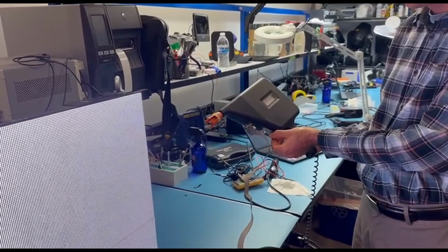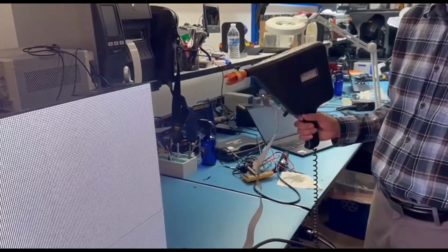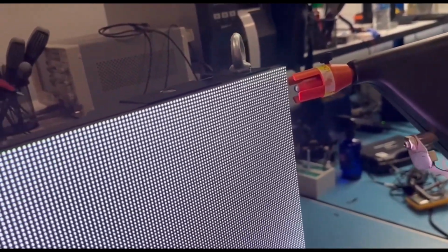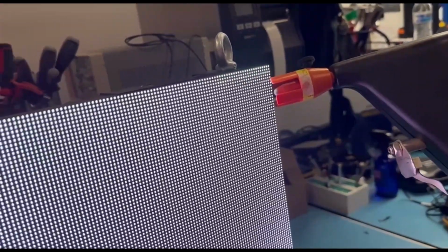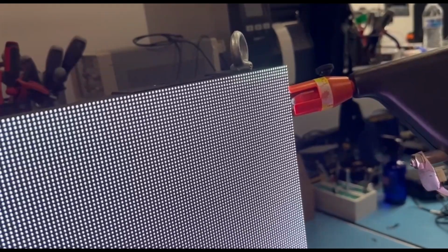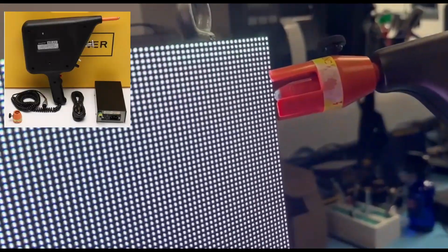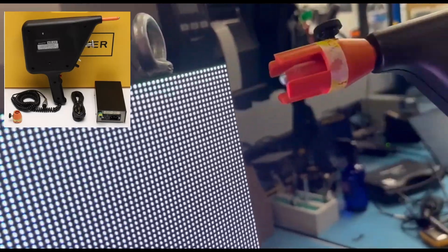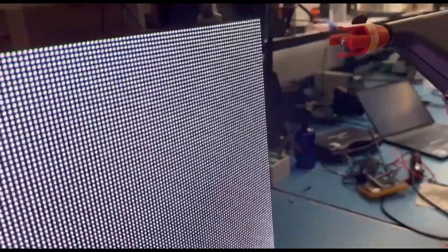At first, the ESD test. We tested the X2V module using the IEC 61000-4-2 standard to evaluate electronic equipment like LED panels for electrostatic discharge immunity. In our lab, we use a Schaffner ESD meter to ensure our products are dependable and safe. During testing, we simulate real-world conditions accurately.